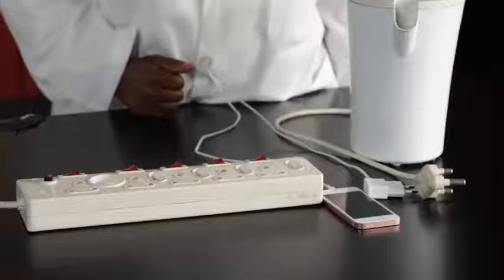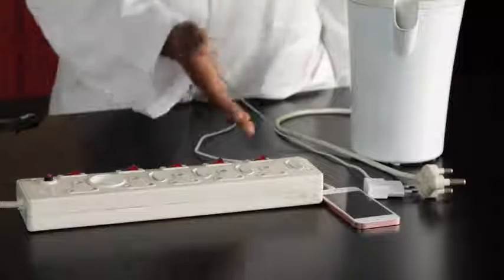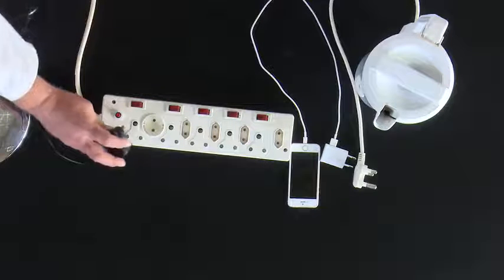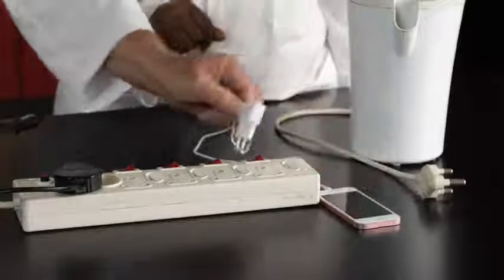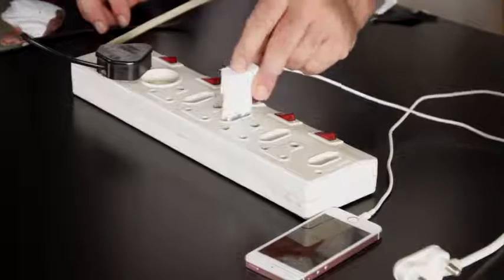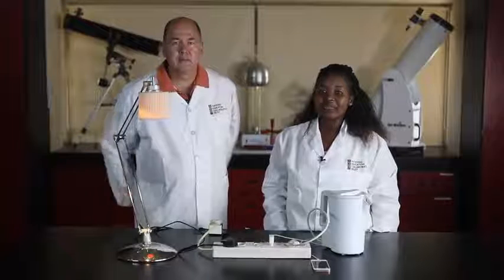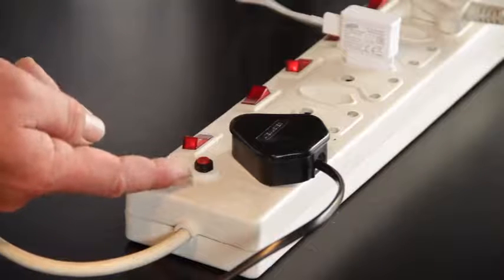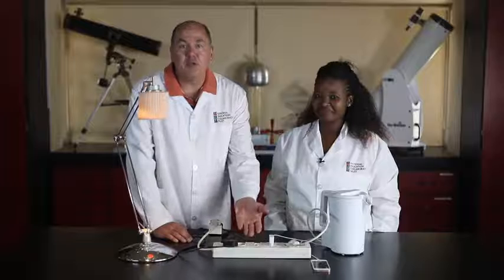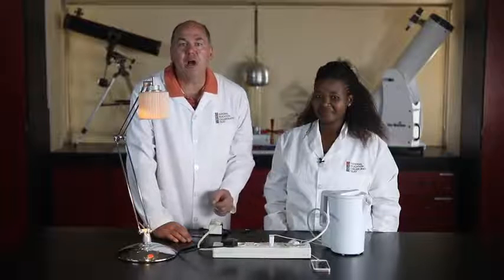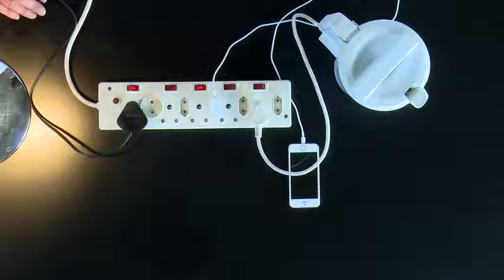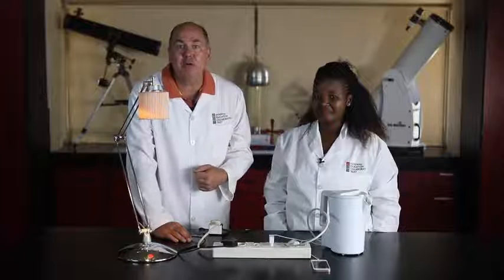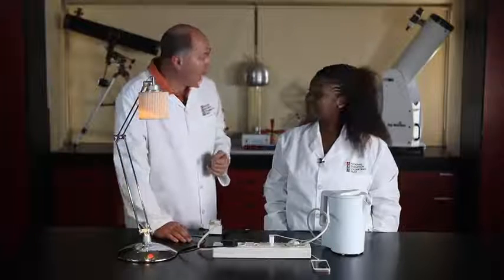When we attach an extension cord with 10 extra plug points on it to an electric plug, we add 10 appliances to work from one particular point. All these extra plug points are wired in parallel to one another so that none of them interfere with any of the others. This extension cord has a little red button which cuts out at currents of more than 15 amps. These types of extension cords and adapters with safety fuses may cost a little more money, but they can save lives as well. They prevent plug points being overloaded with large currents. Large currents heat up the conducting wires and can cause fires in the home.